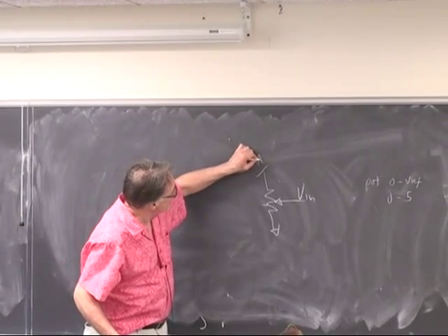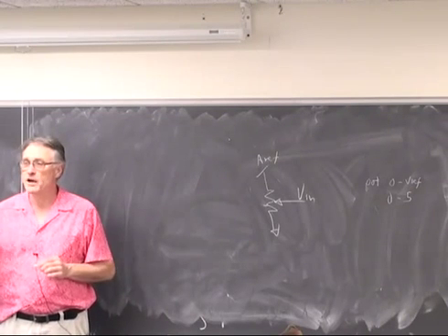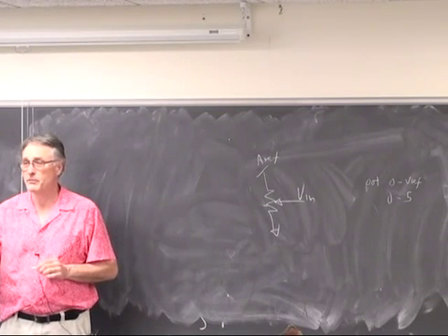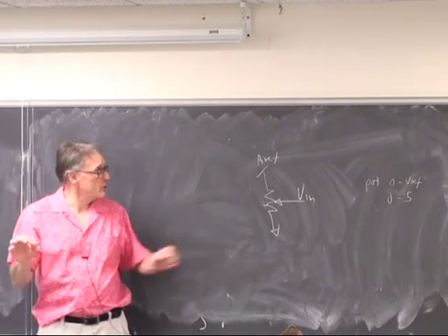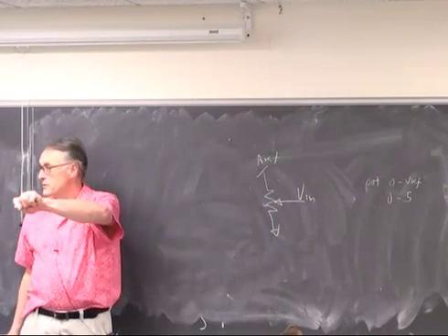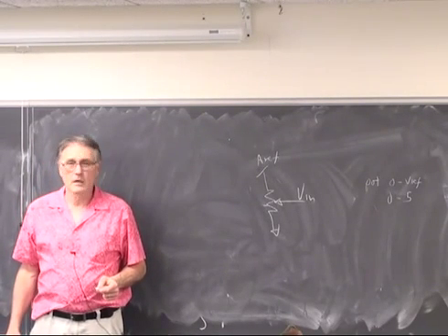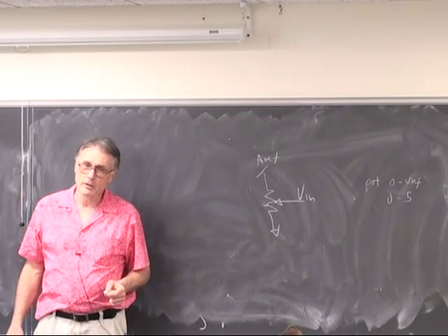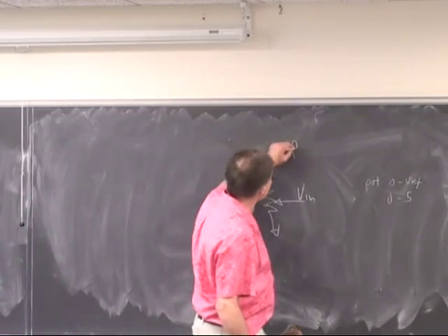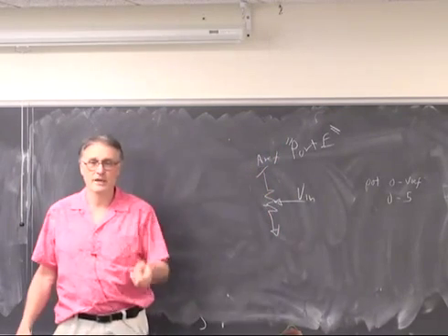So if you want to make this a little more elegant, you can jump this, instead of to 5, you can jump this to AREF. And then as you change AREF in software, the voltage on the pin output from the microcontroller will change, and you will always have 0 to full scale availability for testing the A to D converter. AREF is on a port pin in the middle of the board, right? Port E. It says AREF on port E on the STK500.